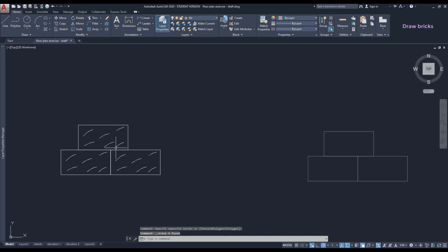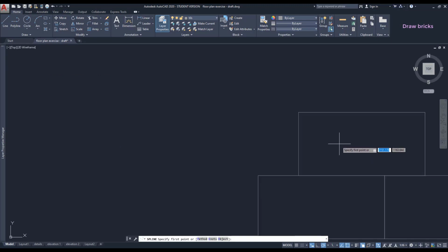Now, these small lines I used here, I draw them with the command spline, for example. That basically makes lines with curves. I click in the points where I want a curve to pass, and to confirm the spline, press Enter. If you press Escape, that cancels the command and you have to draw it again. You can keep drawing lines as you like, and in this part of the exercise, you don't have to follow what I'm doing.